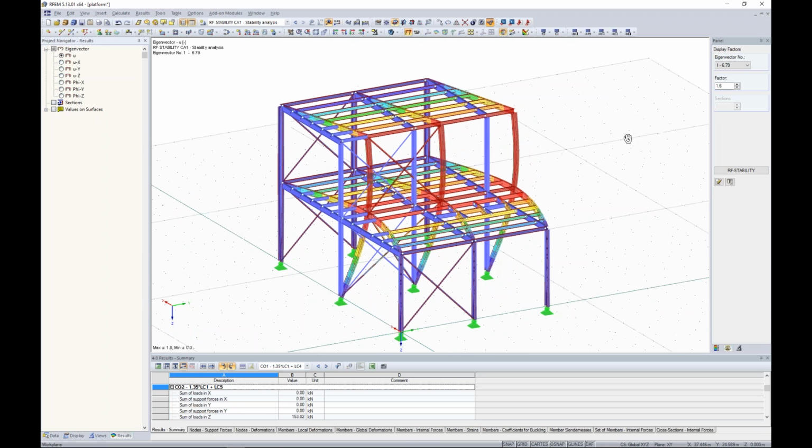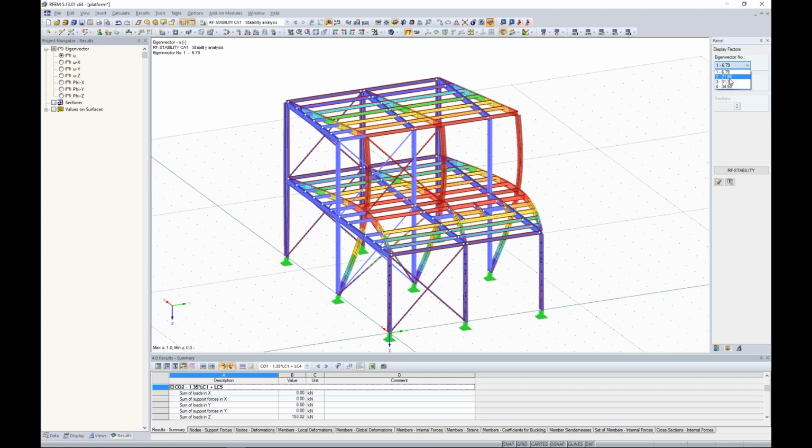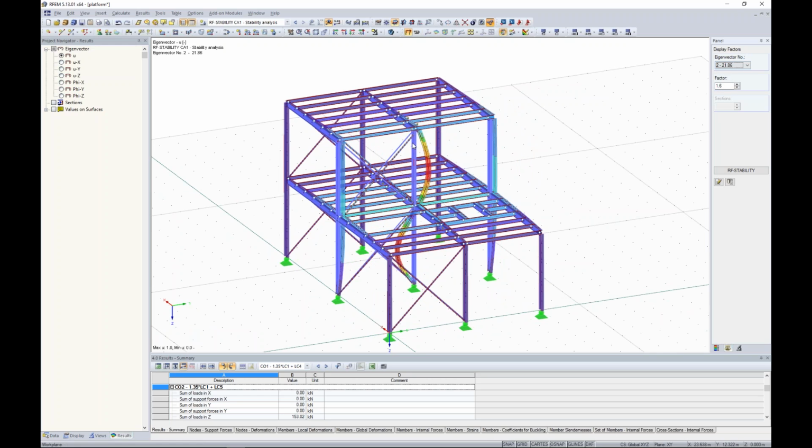theory. If this value is above 10, like the second one, where we have a buckling of the inner column, then it would be okay just to calculate according to first order theory on the undeformed shape, because the bending moments won't change according to second order, and it's fine for first order calculation.